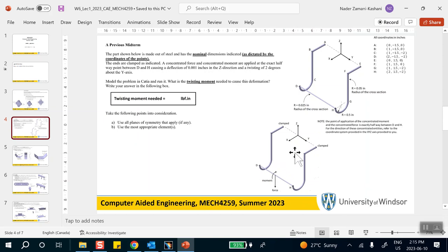And that's exactly what I'm going to do: make half of the model instead of making it and then cutting it. Now, the other thing is that when it comes to this piece, notice that these have different circular cross sections, this piece and that piece. But because this is a planar sketch, you can draw it in a sketch, and don't forget to join it if you're going to go that route.